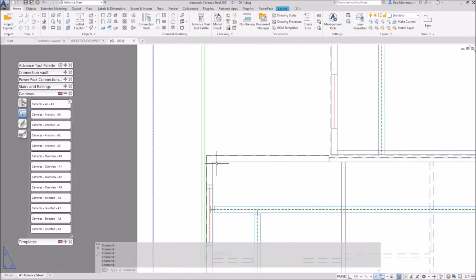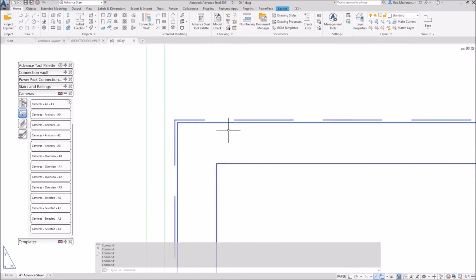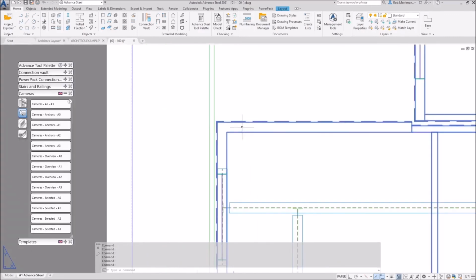Now the reason I modelled the walls in there, if I model the walls, maybe what we should have done is taken out the endpoints, the lines of the walls that we'd modelled, because you don't want to dimension to the endpoints in here. When you update the drawing, that's a point that the system isn't going to be able to track back to the model, and therefore it's probably going to remove the dimension from the end of the beam to the concrete wall. But that is just something that can be done with an architect's layout.